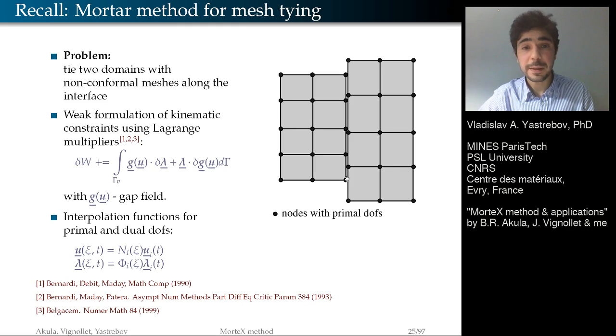and ensure continuous, very smooth stress transition through the interface. It's done actually by weak satisfaction of the constraints along the interface, not pointwise like it's done in node-to-segment formulations, but in a weak form, with surface to surface integrals.